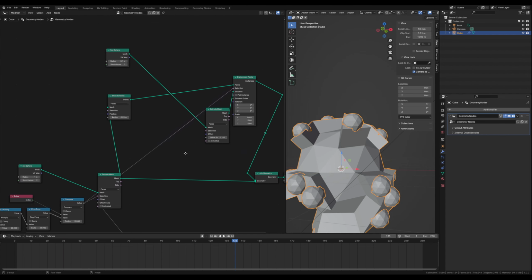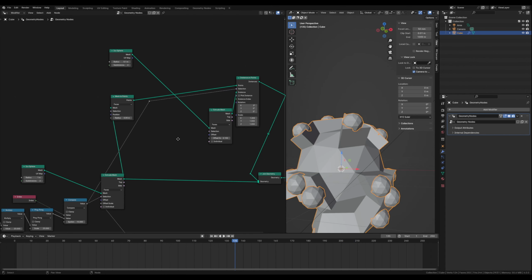So now we want, okay, maybe here also G, okay, and now we want to add to the selection also the compare function. So we can duplicate this, Shift D, duplicate, and connect to the selection.